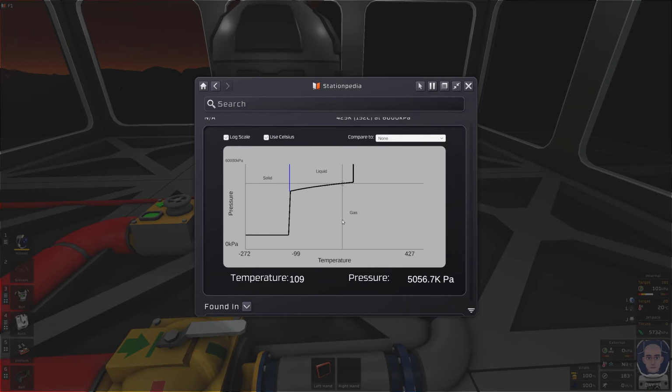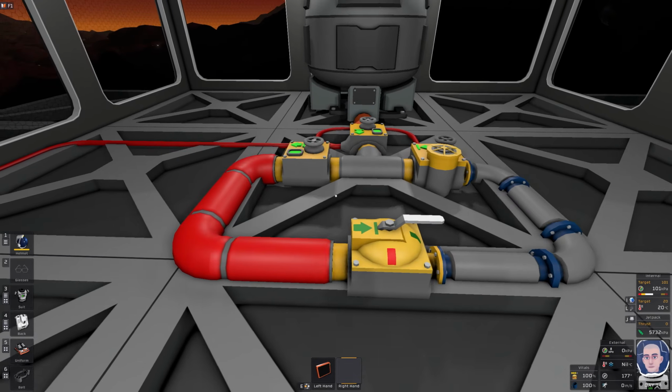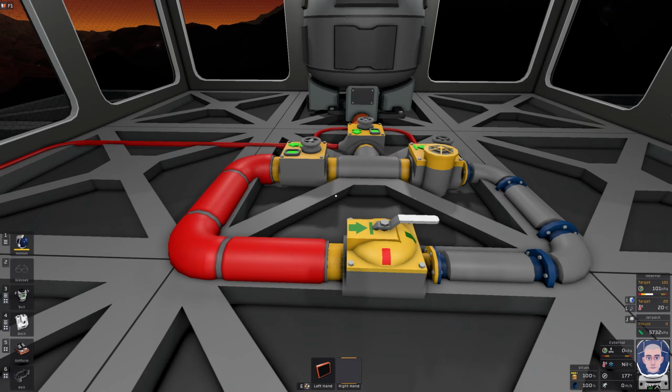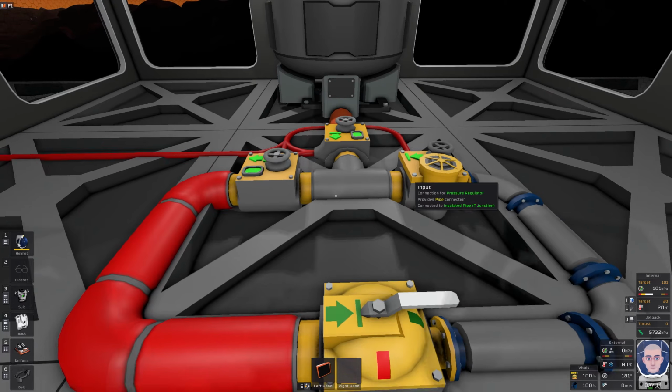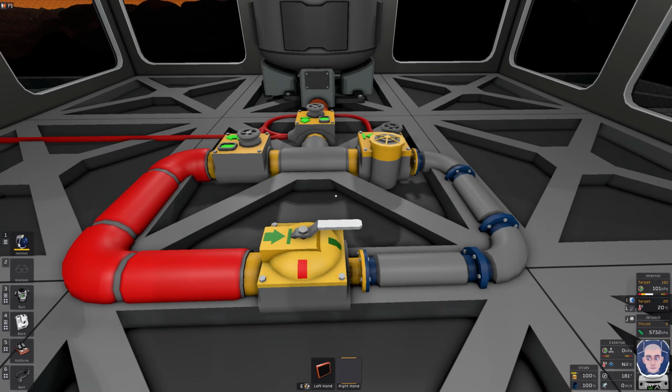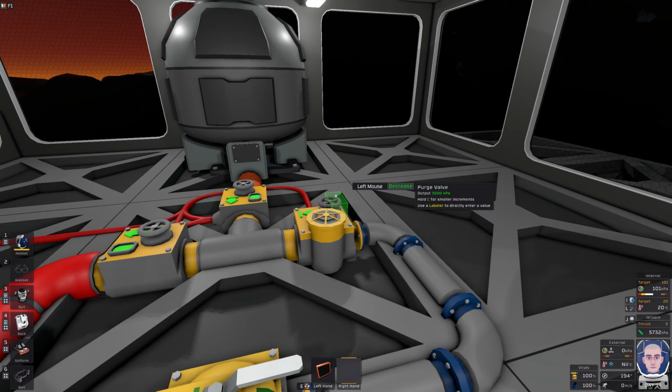Well, that doesn't happen because from experiments, it seems you can get about 50 to 60 degrees Celsius delta. And as you push that, it slows down the process. So say a safe 50 degrees Celsius between stages. So if you want to lower down, say 100 Celsius, you'll need 2 stages. One stage will not do it no matter what you set this at.